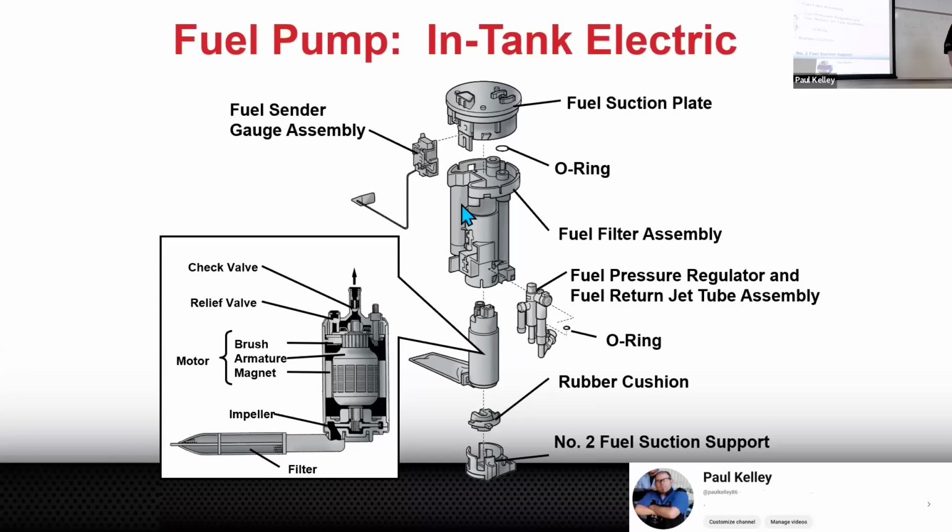However, if you do go to test this, it's not that hard. You can actually go in and measure the resistance right here with your meter set on ohms, right? And you can sweep it. And guess what happens when you sweep it? Your resistance changes. So if your resistance doesn't change as you're lowering and raising the fuel level sensor, you're like, hey, this doesn't work. It's a variable resistor in here.